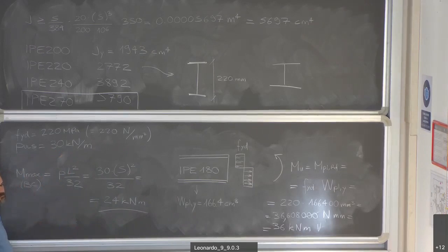How do we know that this is the maximum load that could be acting on the beam? On the basis of statistics or on the basis of some special considerations. Knowing that we are, for example, in a classroom of a university and assuming you students crowd, we know that there will not be a load higher than 300 kilograms per square meter.